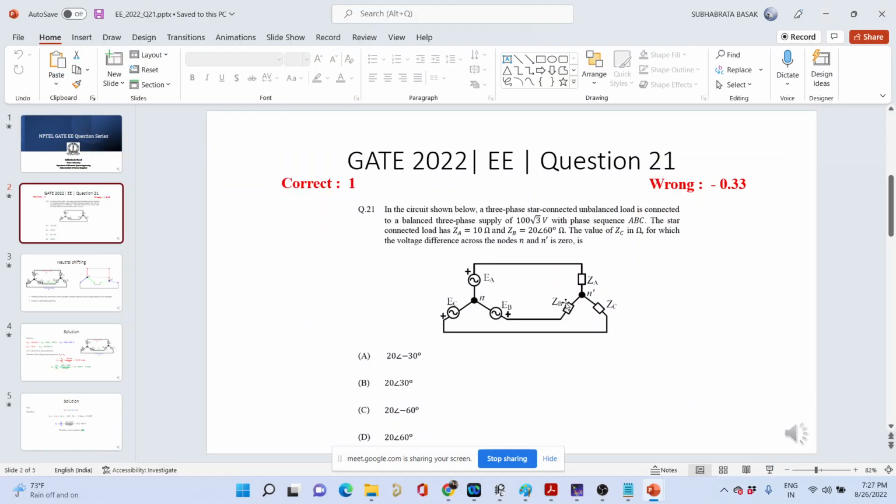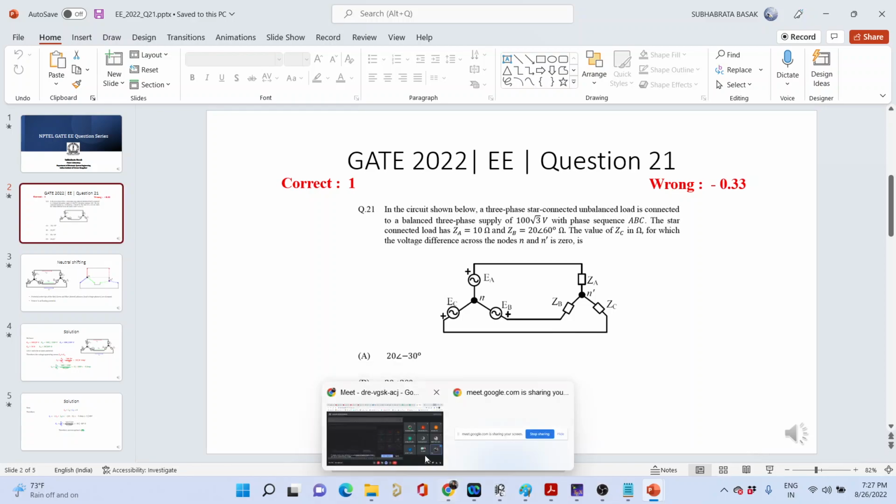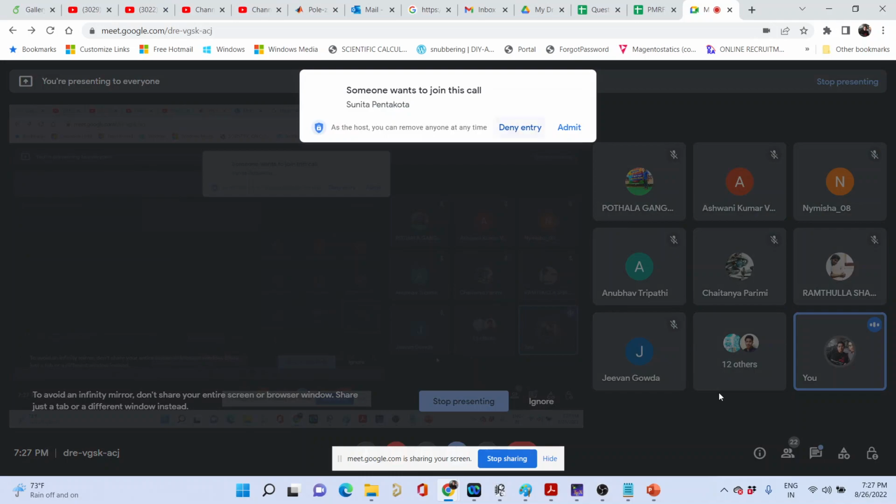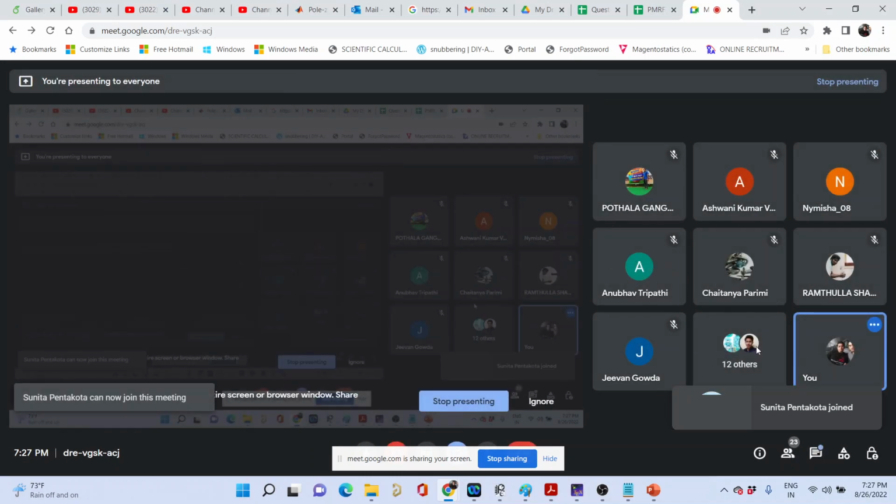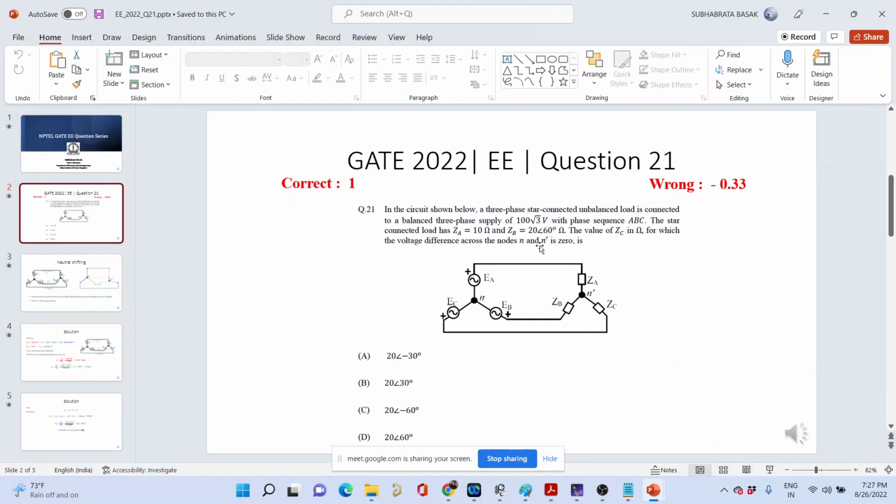Anyways, so yeah, the currents IA, IB and IC would be unbalanced. You are correct. So because of that, what problem are you going to face? What is the problem if I draw unbalanced current? Anyone? What problem can we face if the currents are unbalanced? So neutral current is going to be non-zero. Absolutely. So this question itself gives you a very good example of oscillation of neutral. I hope if you have gone through machines, you have read about neutral oscillation when third harmonic current flows and all. But let's see what happens over here.